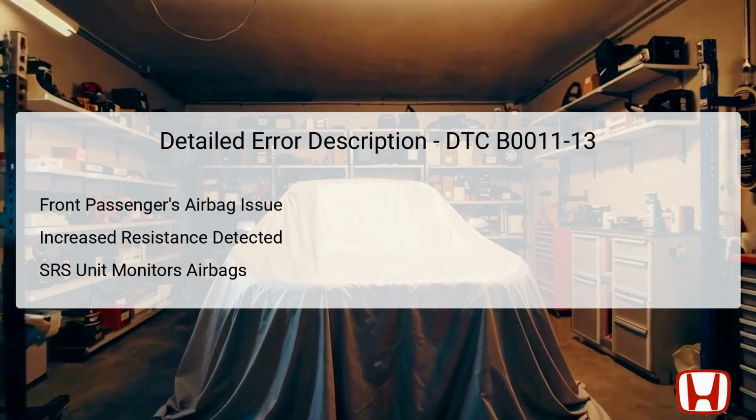DTC B0011-13 signifies a problem specifically related to the front passenger's airbag, primarily an open circuit or increased resistance within the airbag's second inflator system. The front passenger's airbag plays an integral role in the car's SRS, which is designed to deploy airbags upon detecting a collision.